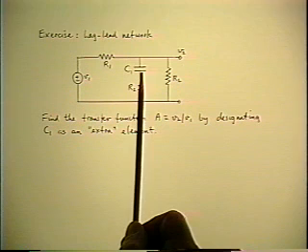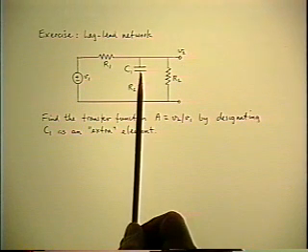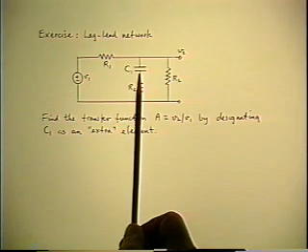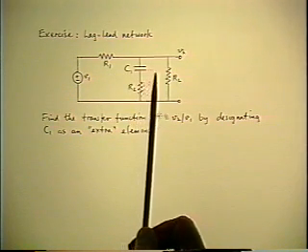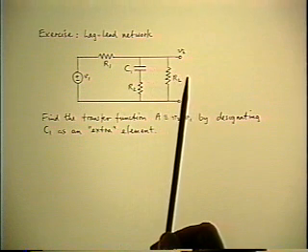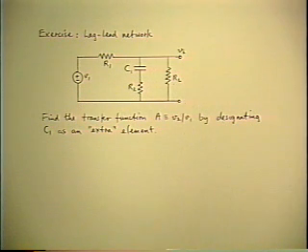If you replace it with an open, the reference circuit is the same as the complete circuit at zero frequency, isn't it? So the reference gain will be the zero frequency gain, and that will come out front in the final answer.